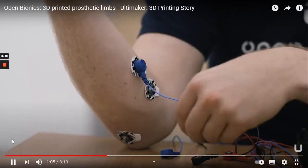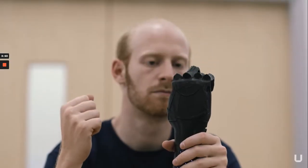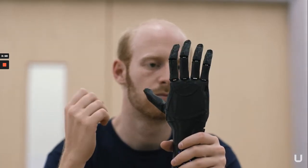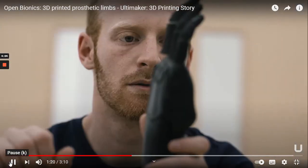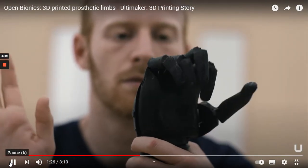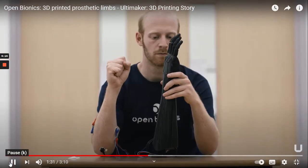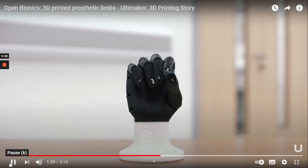We have sensors that we place on the wearer's muscles in their arm, and when they flex their muscles, we detect an electrical signal from the surface of their skin, and that's what makes the hand move. The hand itself has control of each finger independently, and the wearer can give it commands to do different things, so they can move the fingers of the hand with varying power and speed. So they can move it really slowly or quickly and with a lot of power. And they can switch between different gripping modes, so they can do like pinch grips and tripod grips to pick up smaller objects and do fine tasks.